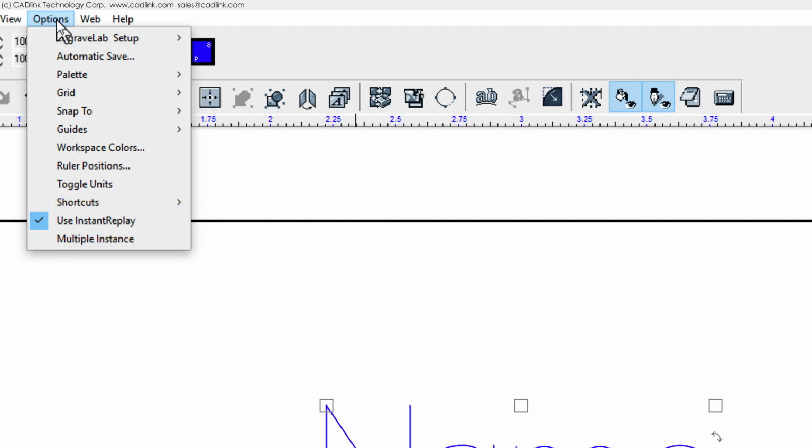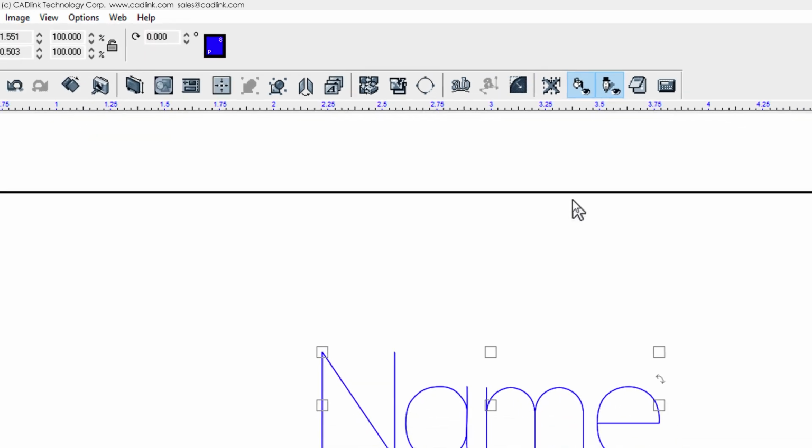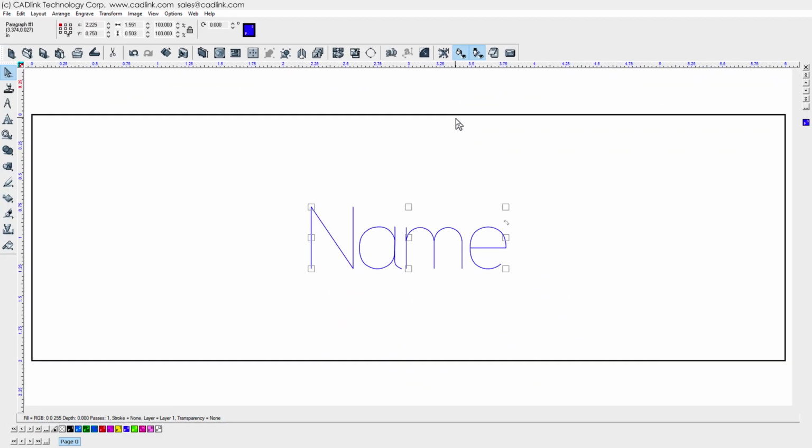When engraving, there are two methods for defining the cutting depth. For the single-line engraving font that we are using, we do not need to apply a toolpath. Instead, you will set the cutting depth at the Machine Control panel, that is to say, when you are ready to output the job. So for this single-line engraving font, no further work needs to be done, and we can proceed with the Badges Setup dialog in the next video.